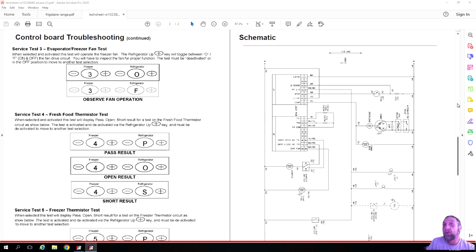Now, I'm not going through the light switch right now, because if you can see, my power is going right to the bulb and my neutral is going right to that bulb. But this board is getting its power from red and white, not red. So something's wrong with the diagram.